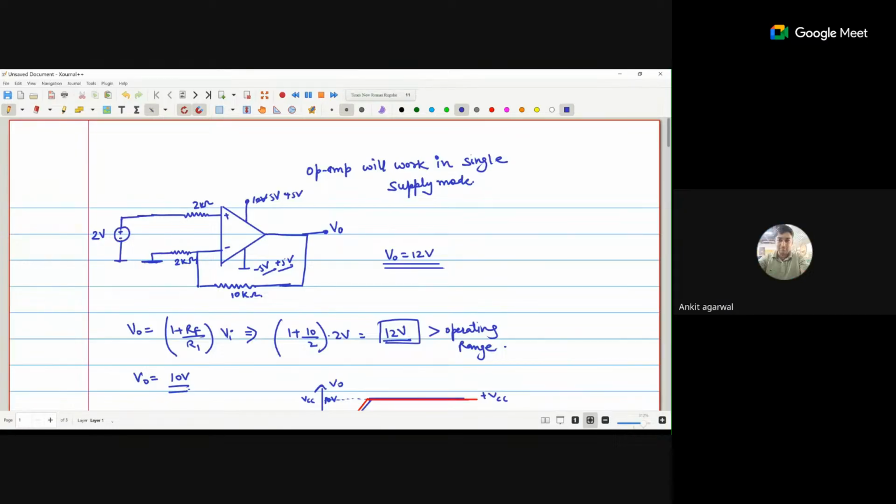Initially my input signal range is minus 5 volt to plus 5 volt. Now my range is changed from 0 to 10 volt, so I can change the input level also, so my range remains maintained. That's why I just use one VCC of 10 volt and apply the voltage divider. With 10 volt across 1 kilo ohm and 1 kilo ohm equal resistances, the drop is constant, so here we are getting 5 volt.